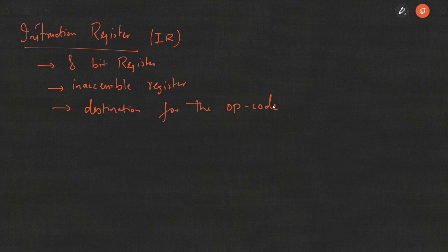The opcode fetch machine cycle is the first machine cycle of any instruction, and in its T1 state, the instruction register will be loaded with the instruction that is obtained from the memory of the microprocessor. Fine. Not in the T1 state, in the first machine cycle.